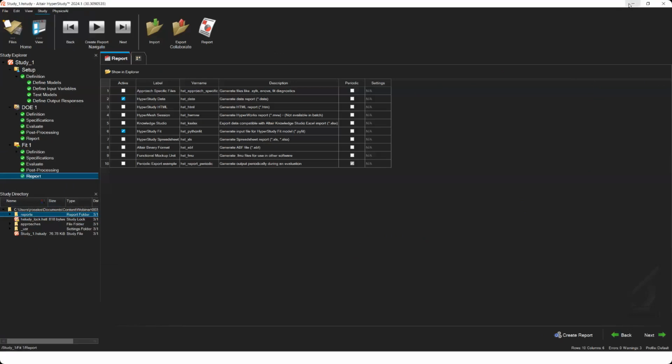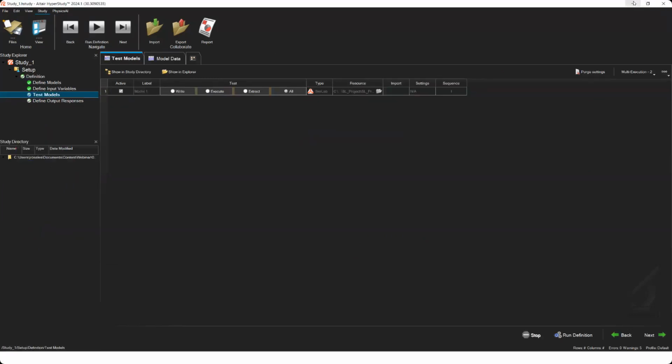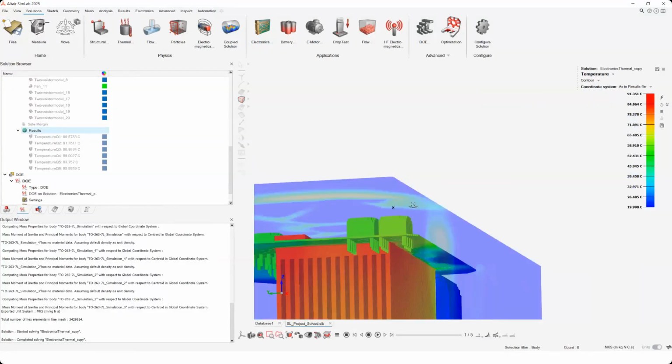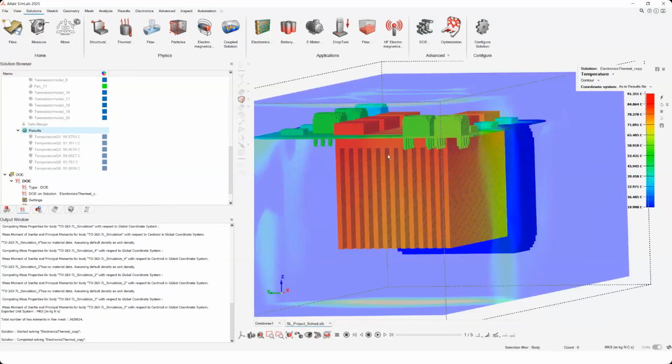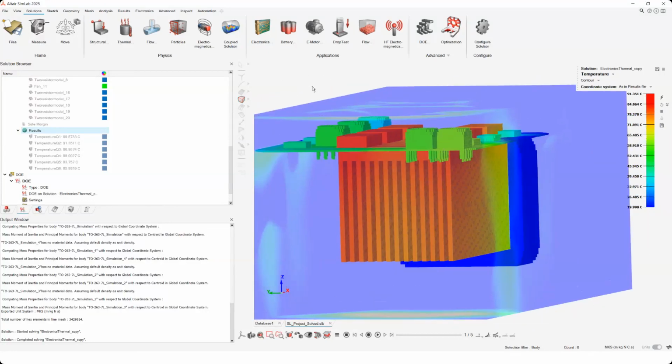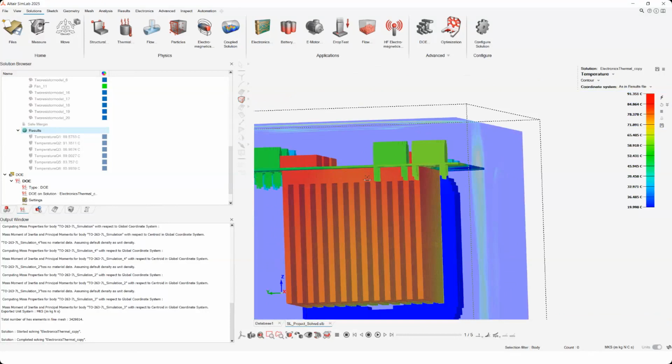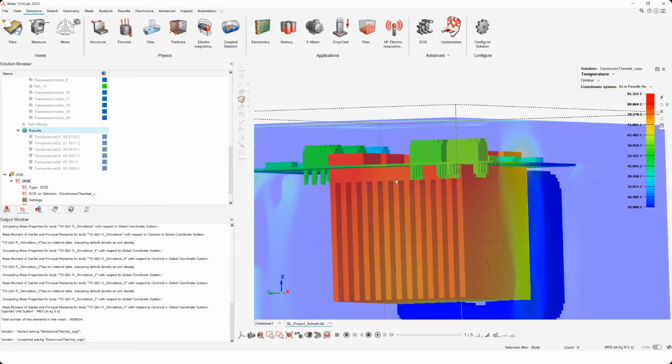But yeah. Okay. Let's see, we have another question about interfacing the heatsink with the board. At the moment, the heatsink is directly on the board, just for simplicity's sake. But there are two ways we can include a thermal interface material. One is by literally including the geometry, so a laminate body between the heatsink and the board, and then assigning the correct material to it.